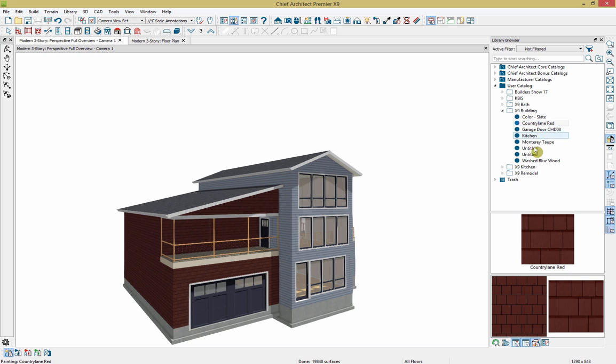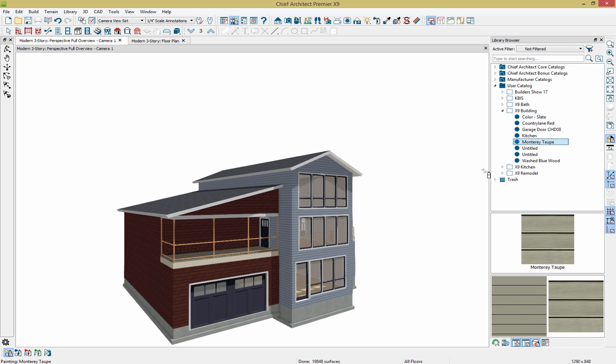And next, I'm going to use a different material for the rest of the house. So instead of clicking on each individual wall, down in the bottom here, we do have additional options on how you're going to apply that material. So I was in component mode for each individual wall. You can do room mode. So if you wanted to change all of the different cabinets in one room, you can do room mode, floor mode, or plan mode. I'm going to get into plan mode since this goes across multiple floors and so forth. So that really changes the scope of how your material is applied.